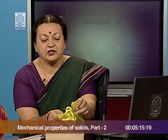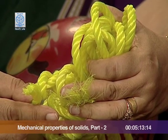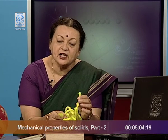So, what is done is that you have these thin wires like this, which make up the entire rope in this manner. That means, you do not compromise on the strength of the rope, and you change it by making it a composite unit of thin wires, so that it has its flexibility and it can be used wherever you require it.